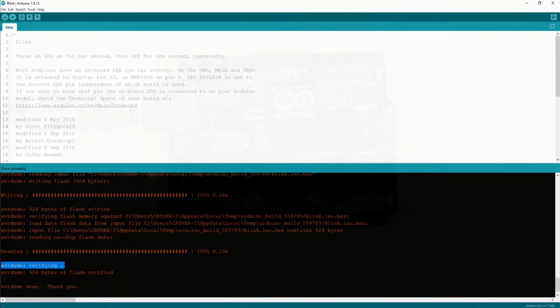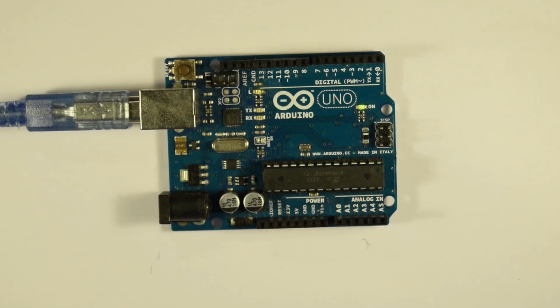And that's it! All of that happened in a few seconds. We now have a LED blinking on our Arduino board. You will probably never need to go further into the compilation process than what I have shown here, but enabling the verbose output and knowing what happens when you upload a sketch to an Arduino can be really useful for fault finding. And if you do want to dive in deeper to microcontroller programming outside of Arduino, this has barely scratched the surface, but it is a start.